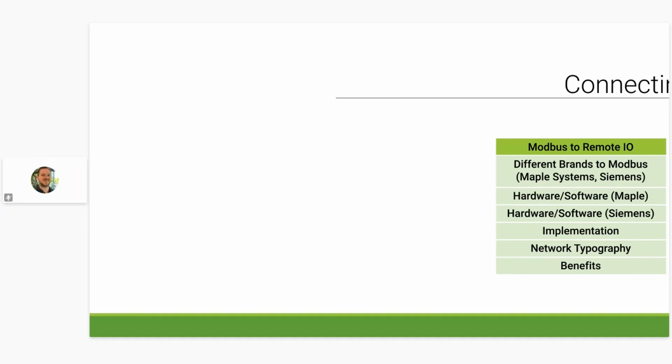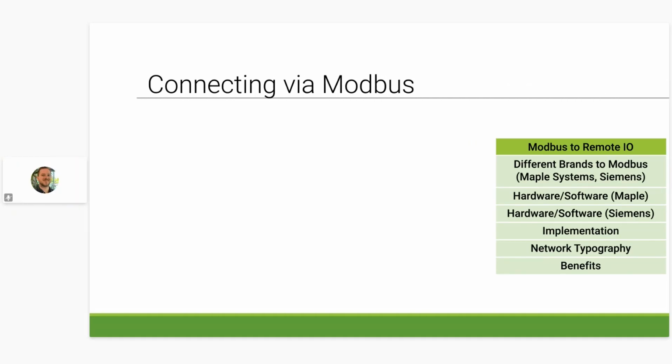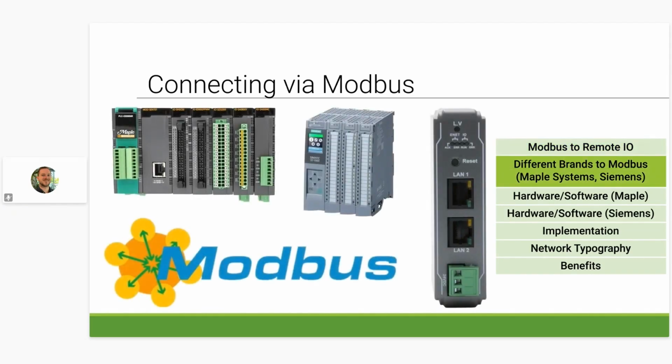Before we move on to discussing some specific case studies on remote I/O use within an actual industrial application, let's first discuss a couple of the most common communication protocols within remote I/O use. The first communication protocol that we will look into a bit more is Modbus TCP/IP. As I mentioned previously, Modbus is one of the most common communication protocols within the industrial automation field and has become widely adopted by many well-known manufacturers. Most devices you choose to implement into your applications will have Modbus compatibility.